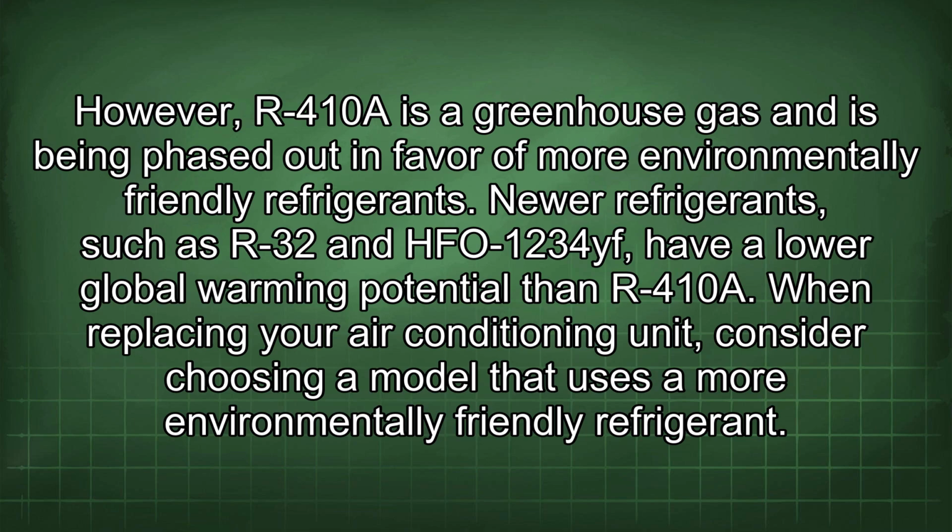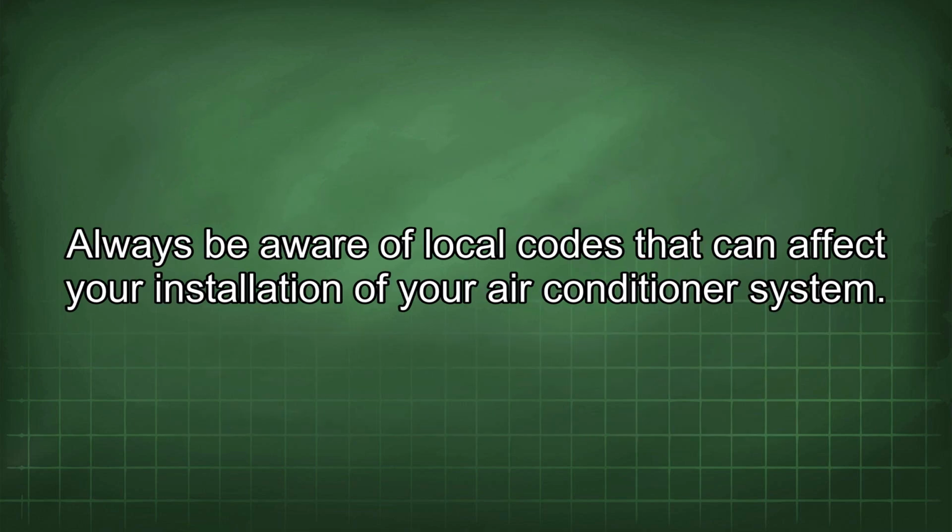Newer refrigerants such as R-32 and HFO-1234 have a lower global warming potential than R-410A. When replacing your air conditioning unit, consider choosing a model that uses a more environmentally friendly refrigerant. Always be aware of local codes that can affect your installation of your air conditioner system.